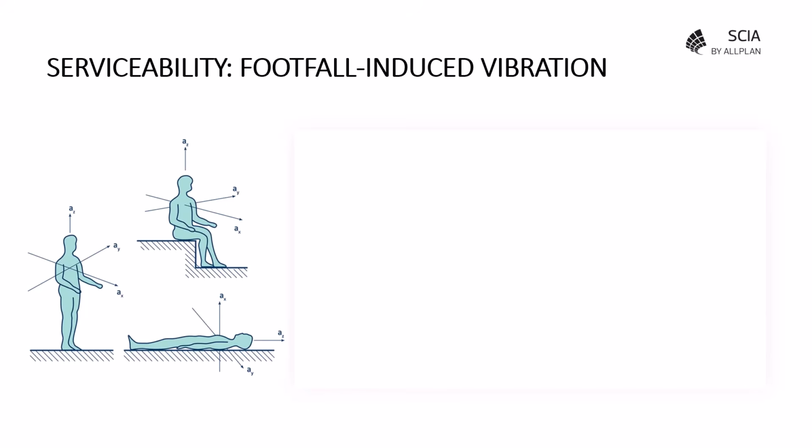Footfall-induced vibration is a serviceability issue. Broadly speaking, we're looking at two categories. The first is occupant discomfort. This is where occupants might describe parts of the floor as bouncy or lively. What it essentially means is that the vibration is noticeable enough for them to make a comment or complaint.